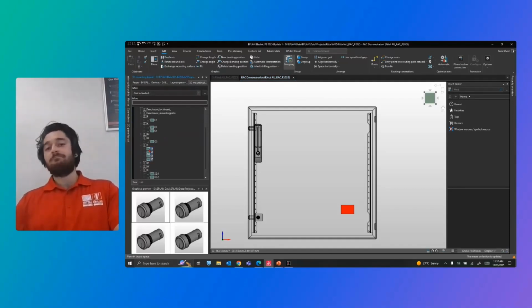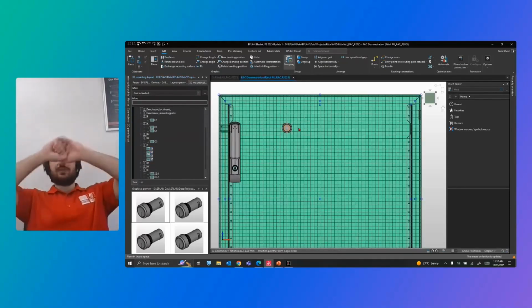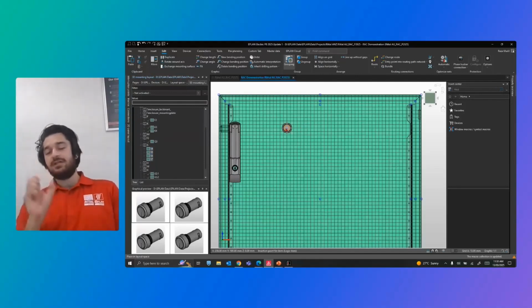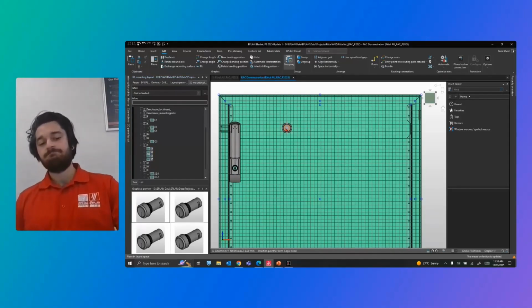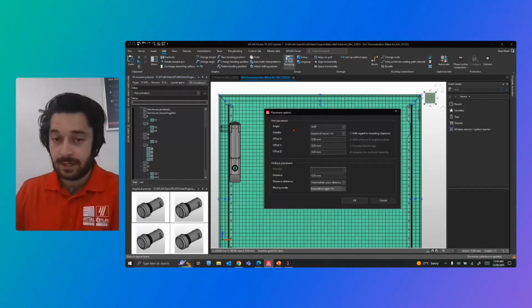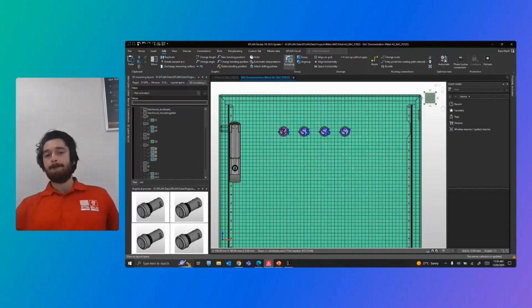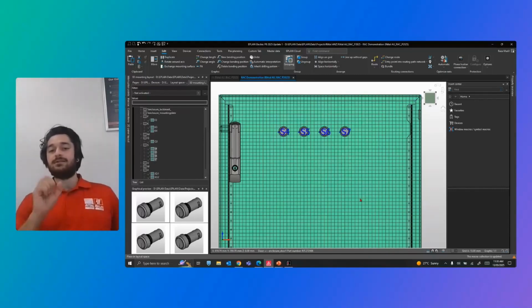Now, another interesting thing. I wish to give them a 60 mils centered distance before placing. I can say, okay, 60 mils centered from left to right. So the moment I place this here, you can see the distance coming in.